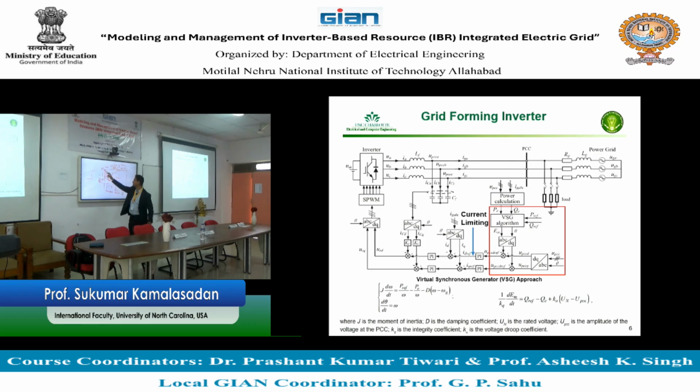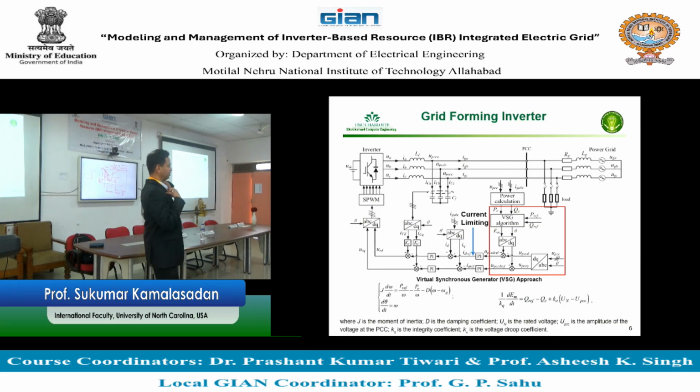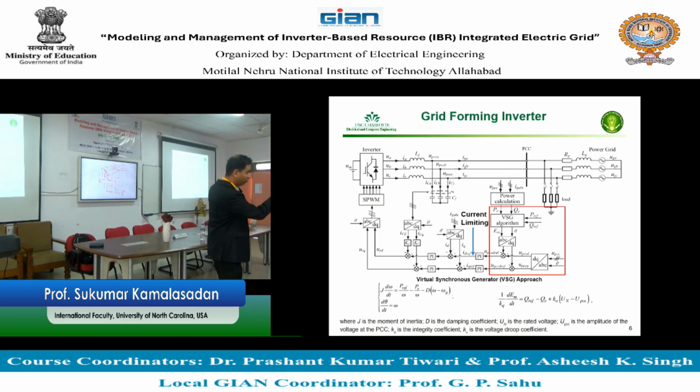The slope is now becoming like this. If you are looking at this line, it's the battery line, and because of that slope it's lifting up. That's what we generally call fast frequency response. There is something in the new literature, fast frequency response, which is generated obviously by battery, no virtual inertia.